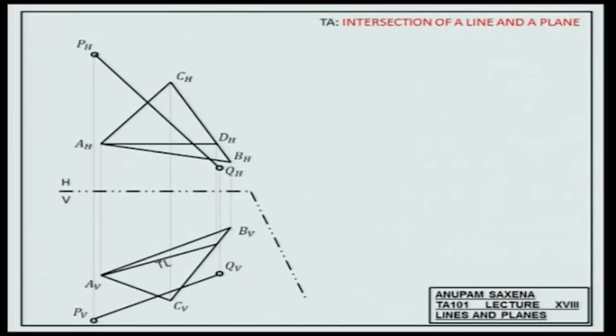Okay, make a hinge line perpendicular to that line, AVDV, shoot the projections out and measure distances. That distance gets transferred over there, this distance gets transferred over here, and the third one gets transferred over here. And this is how you get the edge view of a plane, something which is quite clear to you now.